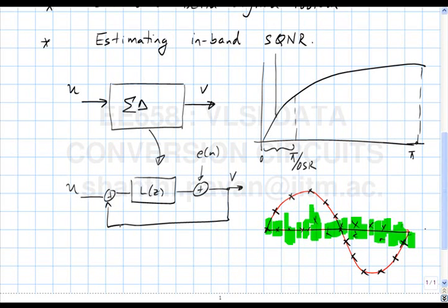Intuitively, what is happening is the following. When you take a rectangular window, a chunk of data, and compute its DFS coefficients, you are assuming that the sequence is periodic, and you are finding the Fourier series coefficients of this periodic extension of the record. For the signal part there is no problem at all, you will see a single spike because the signal is nice and periodic. If I copy and paste an adjacent record after this record, there will be no jump between the two records because the signal happens to be periodic. But noise by its very nature is not periodic at all.